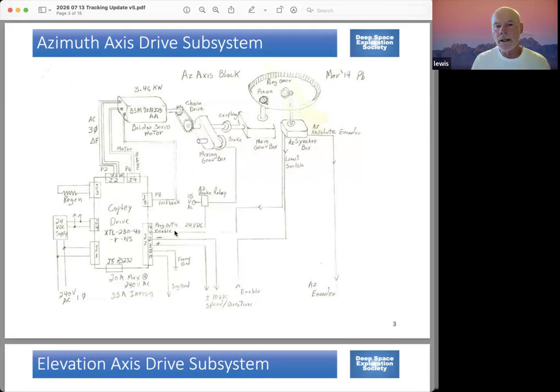And the other note is that when you deassert the enable, the controller will ramp the motor down to 0 and at that point fire the brakes. And actually, I think the firing of the brakes is a timer started at the time it starts ramping down the motor rate.